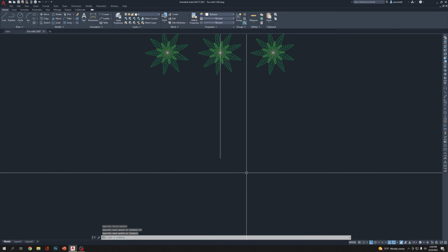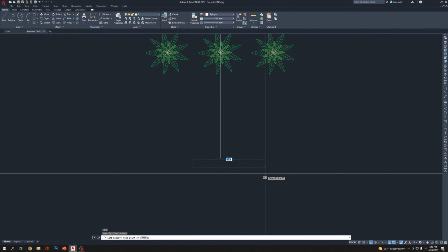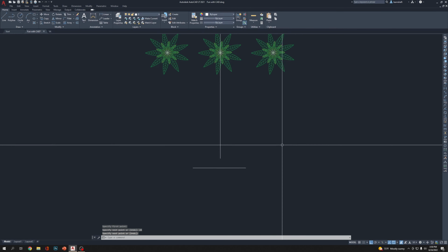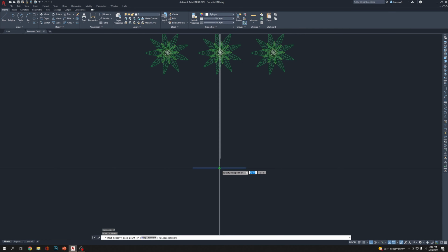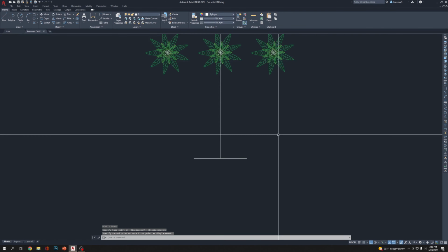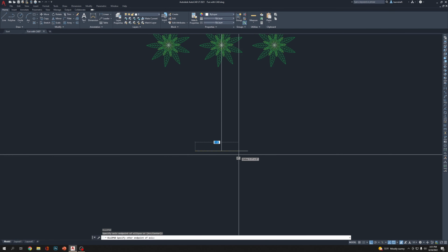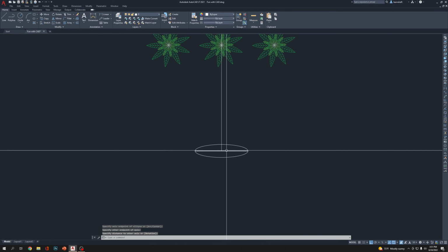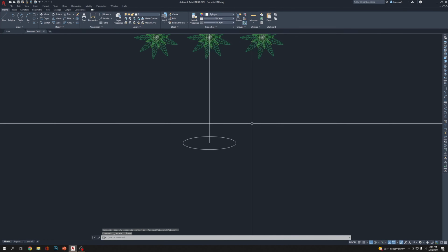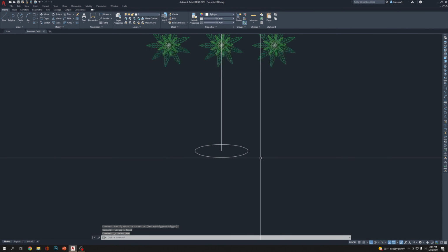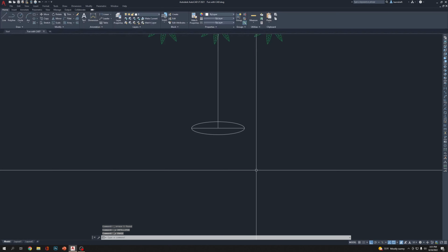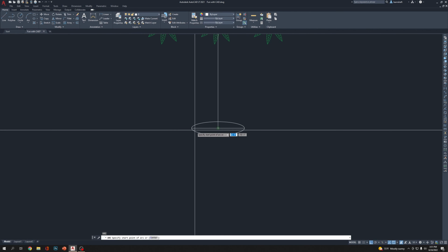And then we're going to draw a line like 24. Select this line from the center point, put it there. Then we're gonna draw an ellipse. EL, enter. So click here, click there, then pull it back. There you go. Now Ctrl Z. I'm gonna keep the lines to draw something else. A, enter.